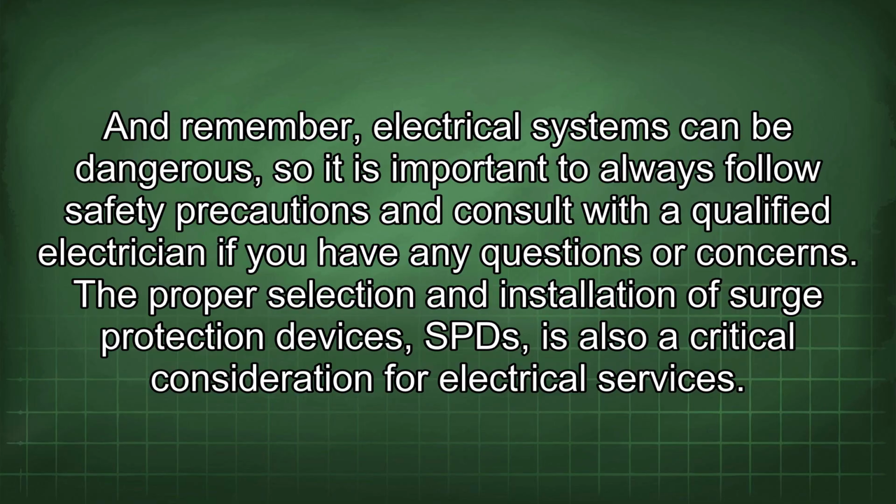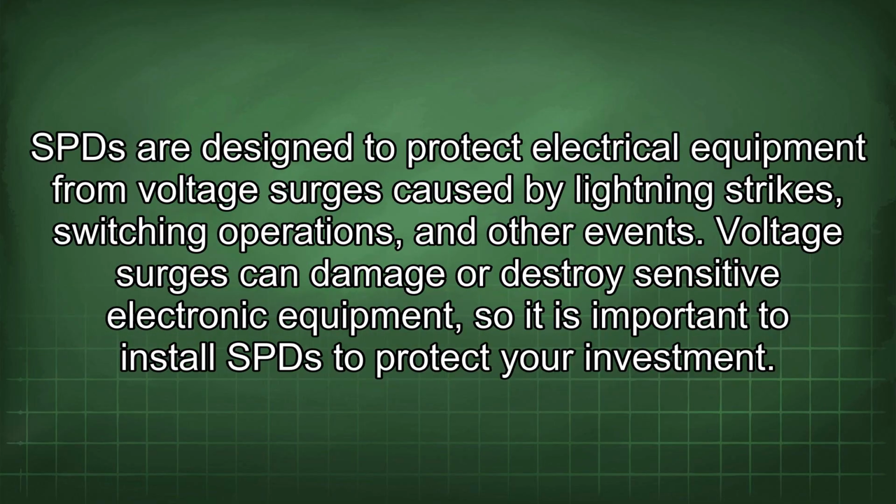The proper selection and installation of surge protection devices, SPDs, is also a critical consideration for electrical services. SPDs are designed to protect electrical equipment from voltage surges caused by lightning strikes, switching operations, and other events. Voltage surges can damage or destroy sensitive electronic equipment, so it is important to install SPDs to protect your investment.